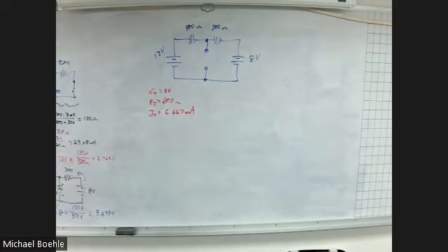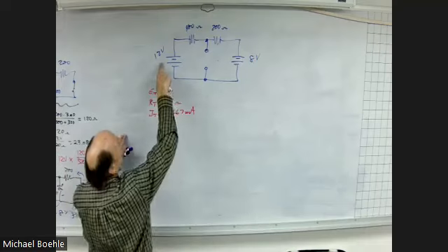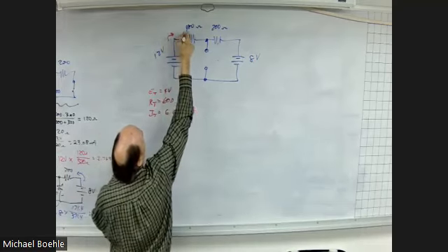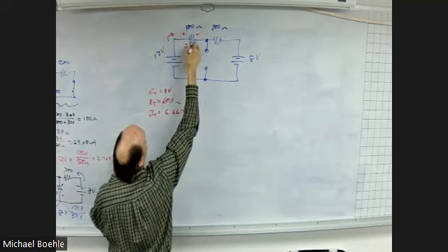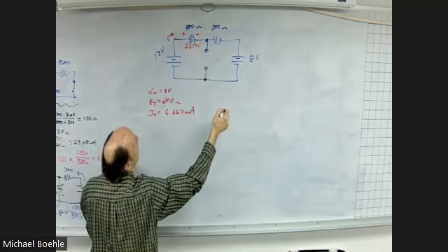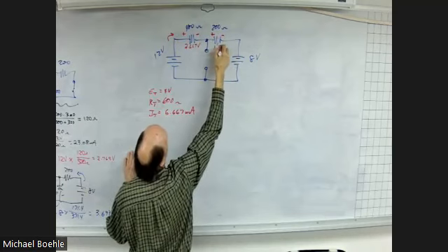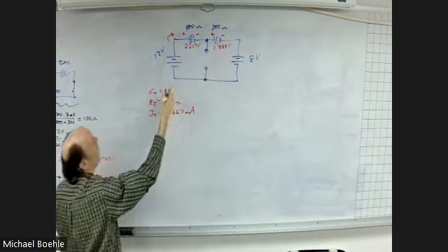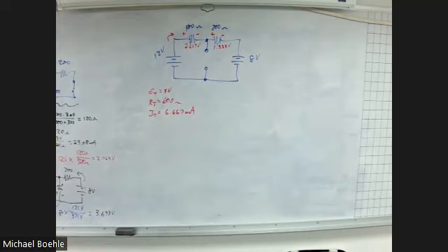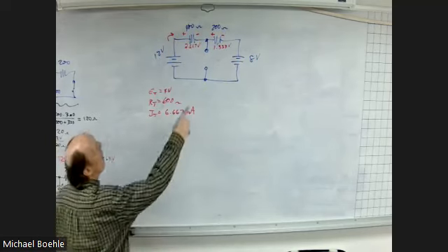It's a voltage drop of 2.66666. Now, because this is bigger, current flows that way. So there's your voltage there, 2.667 volts. And then this will just be half of that, because it's half the resistance, 1.333 volts. Those two, of course, add up to 4. So what is the voltage between these two points?